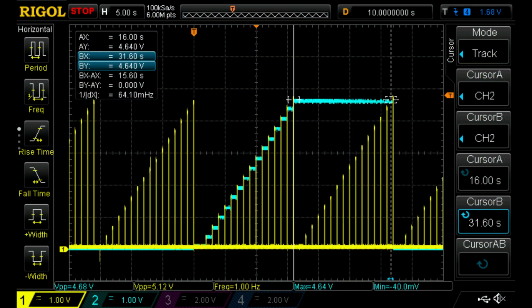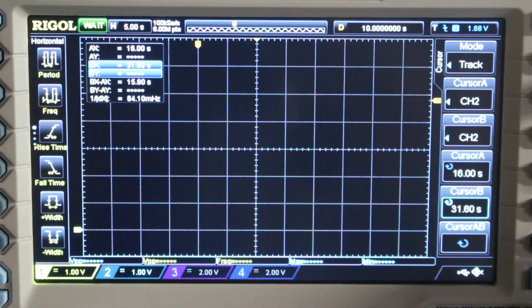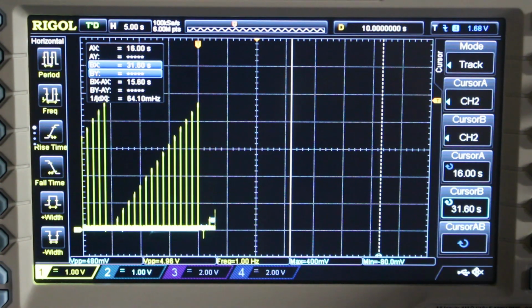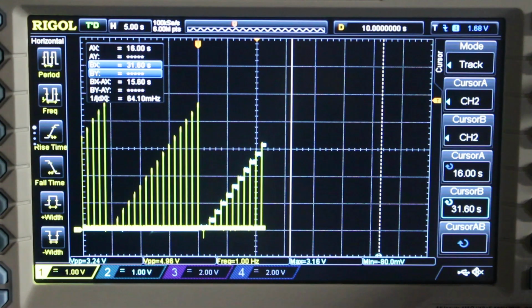Even stretching the hold time out to nearly 16 seconds, I can't measure any leakage at all with this setup. The trace looks perfectly flat. Okay, I'll replace the 10 nanofarad holding capacitor with a 1 nanofarad one. I'll set the scope cursors up for 10 seconds to make the arithmetic easier. The hold times are so long that this test takes a lot of patience. The trace just crawls across the screen. Okay, I'll wait.